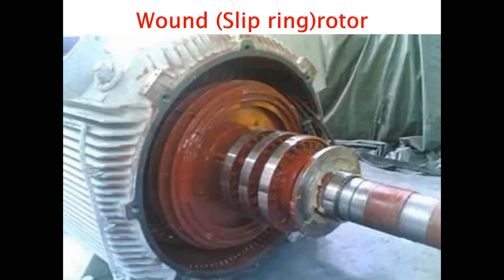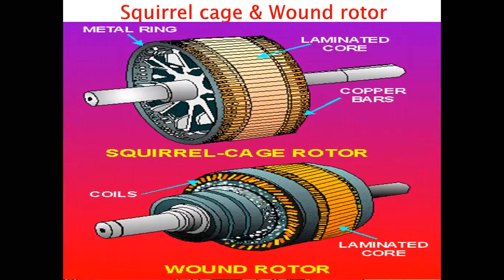But if you see its construction, its assembly is becoming complex because there is a need of additional slip rings and the brush assembly. So it will require regular maintenance. We can say that is a disadvantage of the slip ring motor. And if we talk about the squirrel cage induction motor, its advantage is that its construction is simple. As for its disadvantage, with the squirrel cage you will get low starting torque.